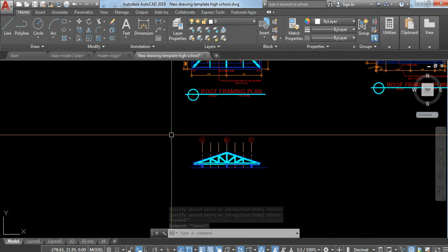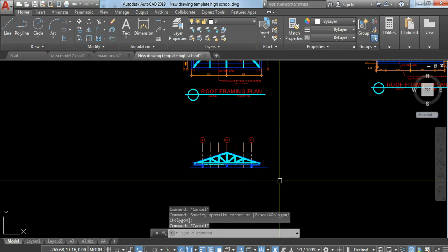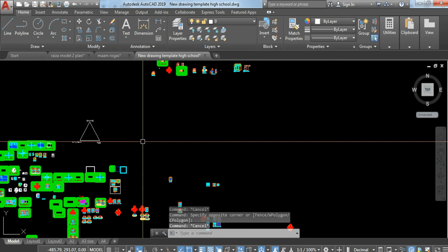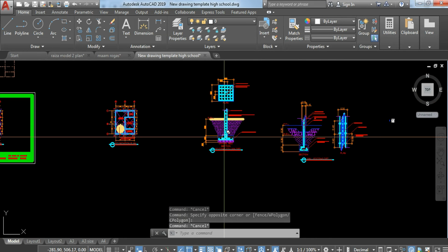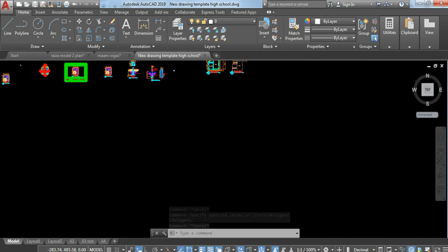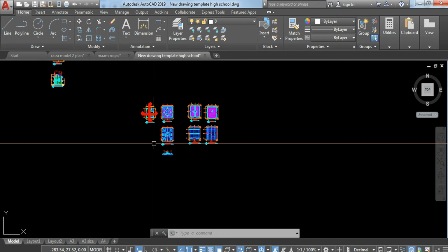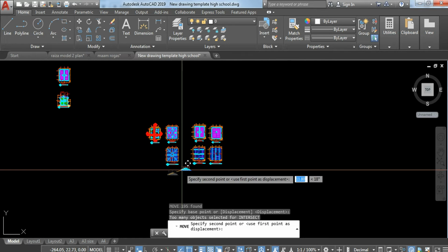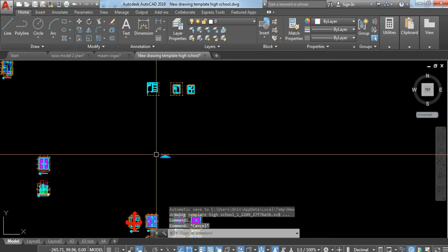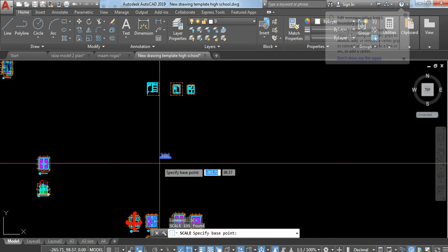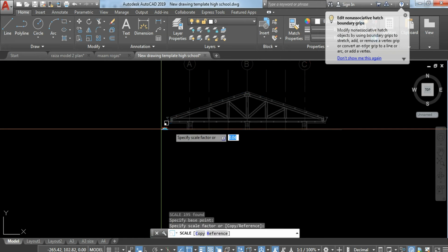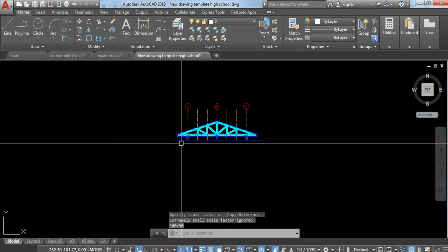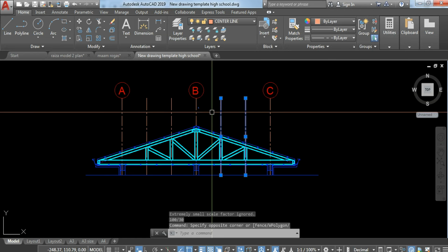and then set the scale into 1:30. Now, always remember, what did you observe when you're going to have details? It's always bigger when it talks about details. So what you should do is simply highlight your work. Move this drawing somewhere here, and then I'm going to highlight, type SC, enter, click your line, type here 100/30. Okay, so it becomes bigger compared to our first design.